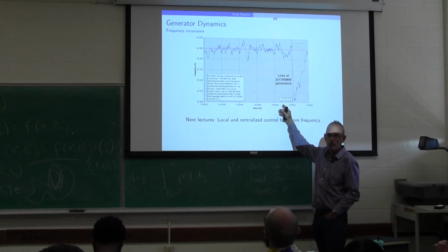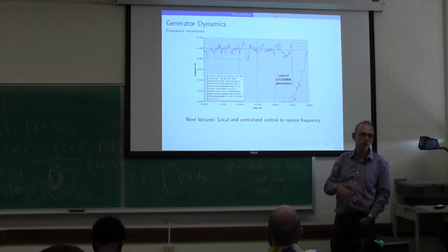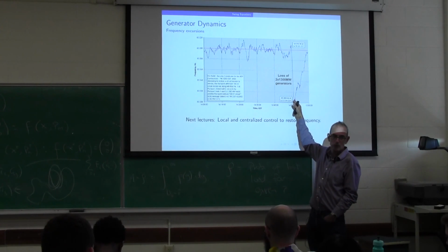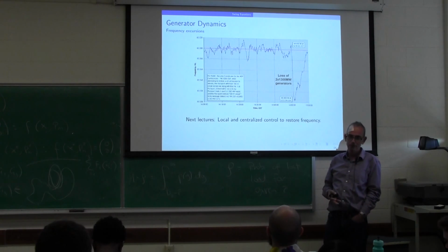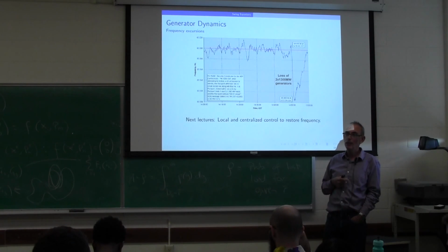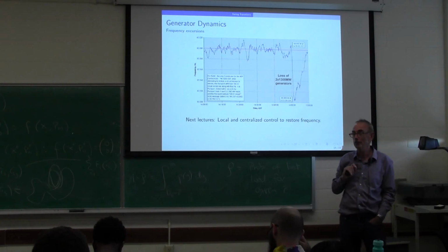Yeah. And it's just the whole, this is Midwest Idaho, it's filled with hundreds of these massive coal generators. And so the collective inertia is huge. And so that slows down the rate of change. That prevents the frequency from dropping too quickly. That's one layer, is just inertia of the grid. And which is disappearing. So there's a real concern about that. In places where they're replacing a lot of traditional generation with wind, they're concerned about that lack of inertia. So the slope here could be steeper depending on how we design the grid.